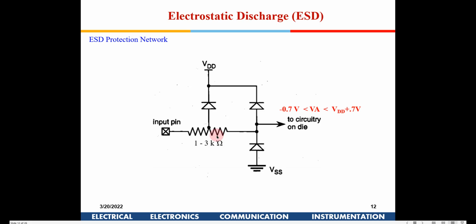Once you design your circuit, before sending it out for fabrication, in the layout as well as in the schematic, you will place IO pads all around, where all the input signals will be passed through. There is an equivalent schematic as well as layout which will be provided by the fab lab. We generally don't design IO pads; it is done by the fab lab, and like you pick up NMOS and PMOS, the same way you pick up IO pads also.